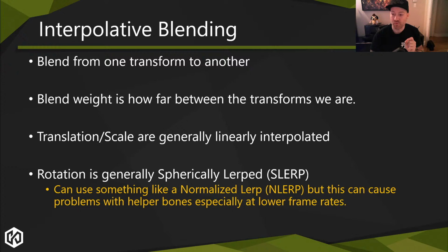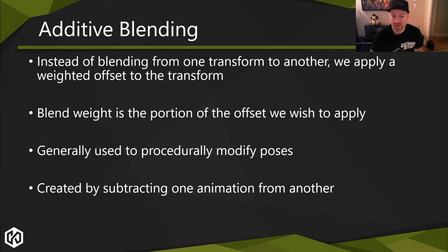This can be problematic if your frame rate is spiking or if it's low. Additionally, those articles will say, hey, it's not a problem, nobody's going to see it, blah, blah, blah. Yeah, maybe 10 years ago it was maybe not an issue when we had like 10 bones. But if I have a massively deep hierarchy or I'm trying to calculate IK targets and now this thing is speeding up and slowing down halfway through, and all of a sudden my IK is going fast, slow, fast, it's an issue. And these days, it's not really that much of a performance concern as back in the day that this is necessary.